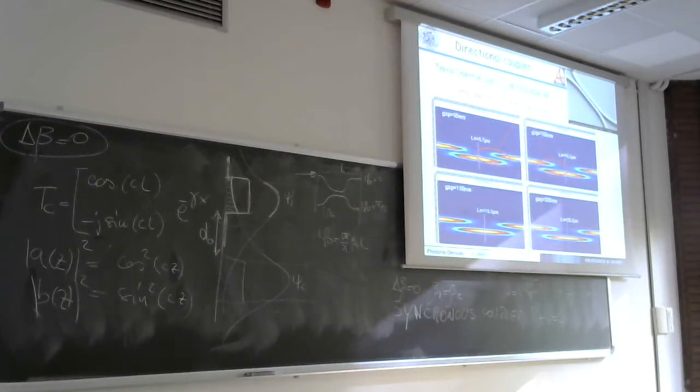So this is just a slide to tell you that the coupled mode theory works very well, even if the waveguides are quite close to each other. If they are too close, then you can have losses, you can have a reflection, you can have a distortion of the field, excitation of higher order modes. So do not couple too much.